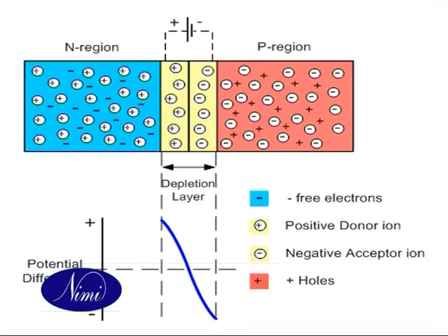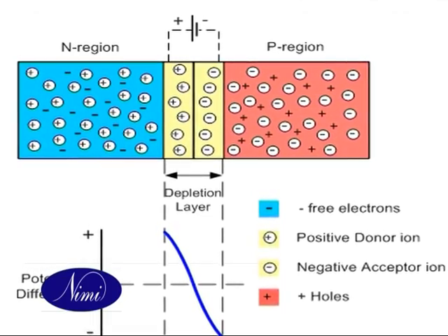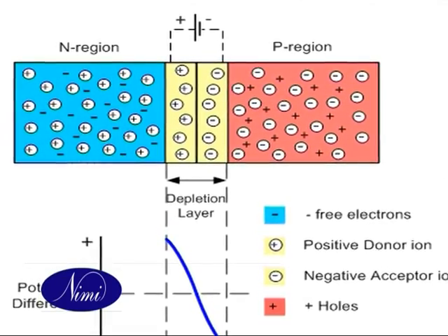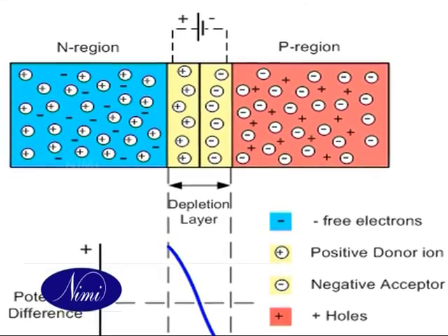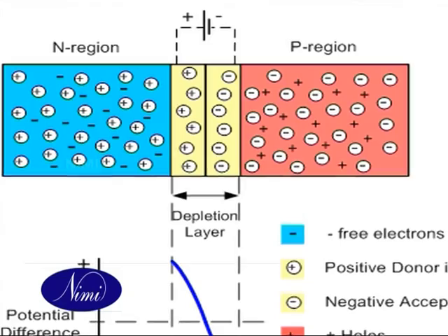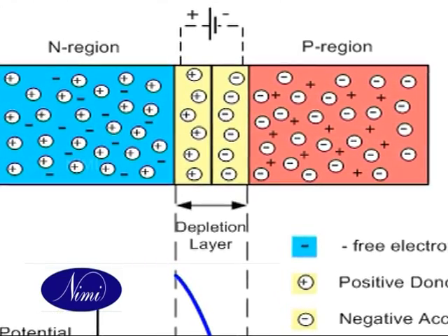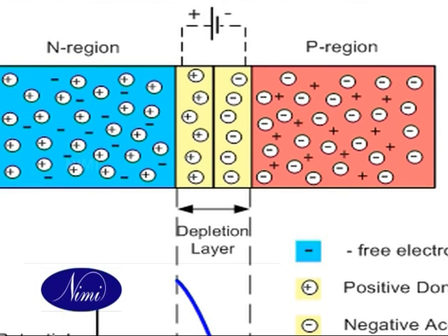The current in the forward direction increases rapidly upon reaching the forward voltage VB, which is known as the barrier potential or the junction potential. The behavior of the P-N junction is limited by the maximum forward current, as too much current may destroy a diode due to the excess heat generation.